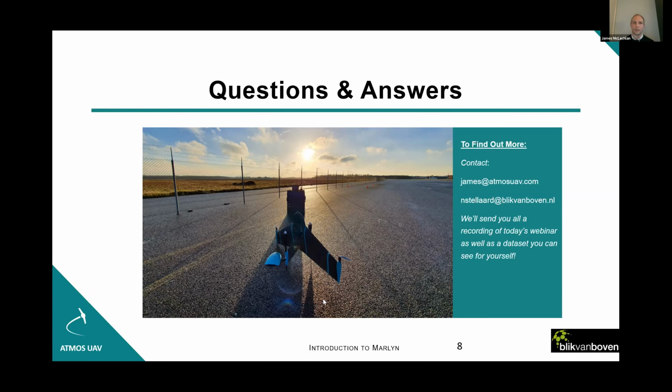Because we have a set of propellers specialized for the helicopter mode and a set of propellers specialized for the airplane mode, we're able to operate at our most efficient operating point for each of those flight regimes, because each of them has a specific RPM and torque that is required to be optimal at that point. I think there are certain drones out there that don't have that, which may limit your ability to operate at flight heights above about 3,000 meters. But with us, it's not an issue.